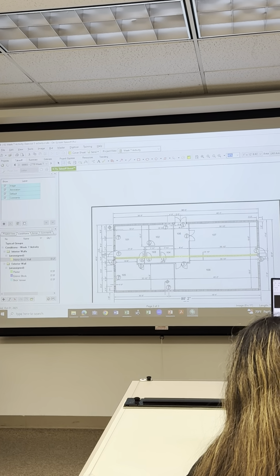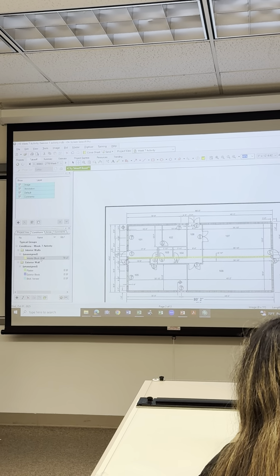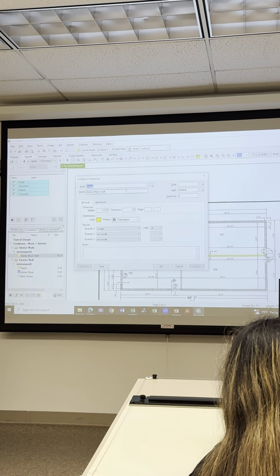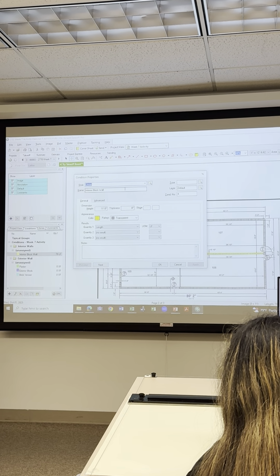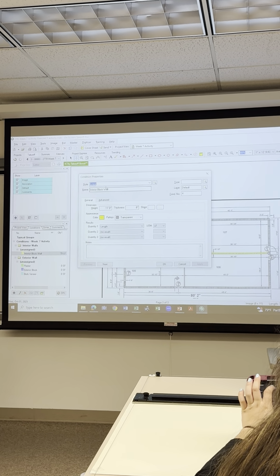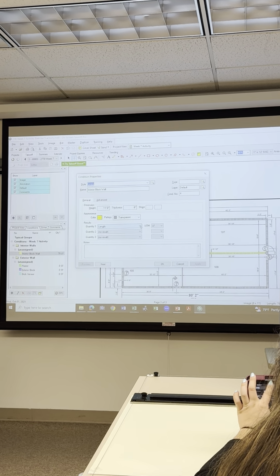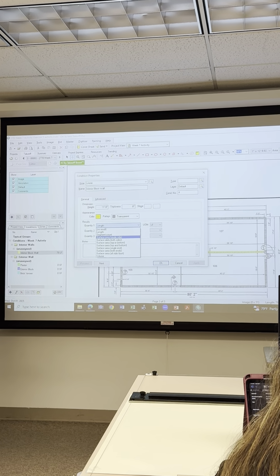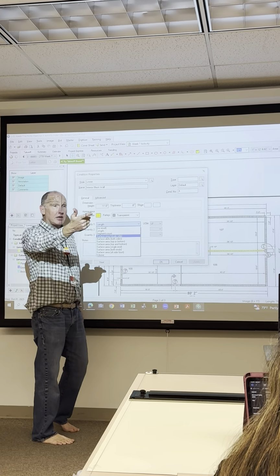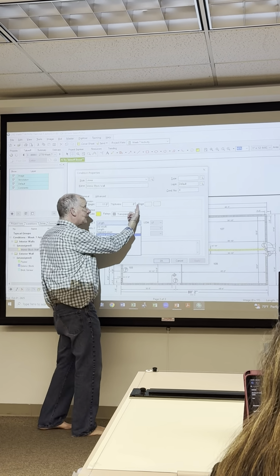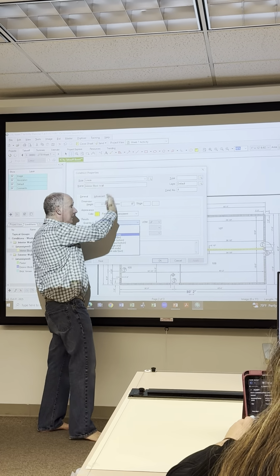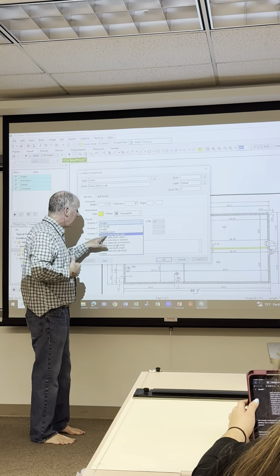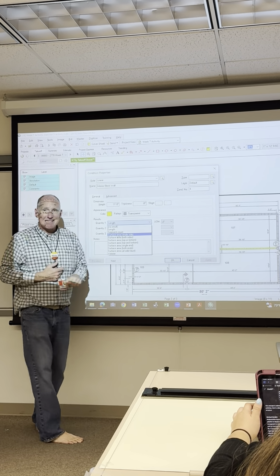And there's my length. It calculated out 78 feet from the inside wall. But the quantity takeoff I want to achieve is area. So we go back to the properties. We do quantity 1, we want to change it to surface area. See all the quantities. Let's say we wanted to grout, just like your height. You do volume, you got the thickness, you got the height, you just calculate the length, you have volume right there. You do concrete. But I just want to do surface area, single side.